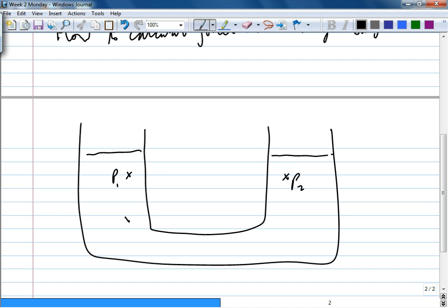If this point here, P3, which is below P2, is the pressure higher or lower than P2? Let's say this head. So P3 is higher than P2, that's why P3 minus P2 is a positive number, equal to rho g h. Rho is the density of this liquid. Okay or not? That's what we calculated, and that's what I showed last week.